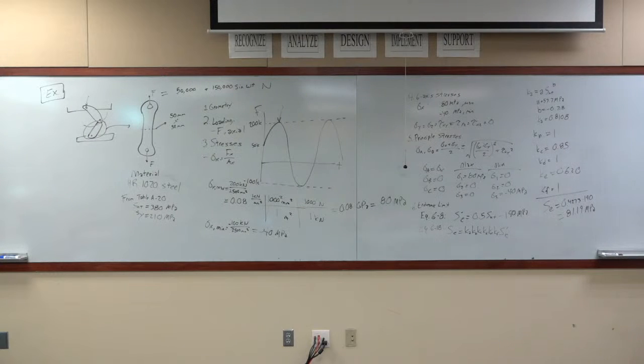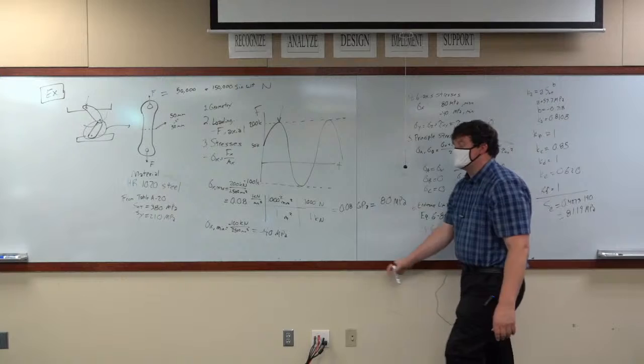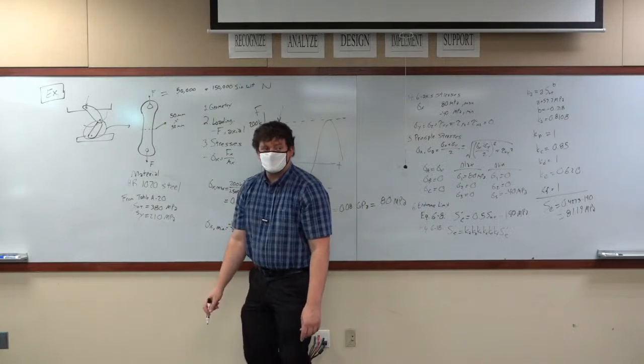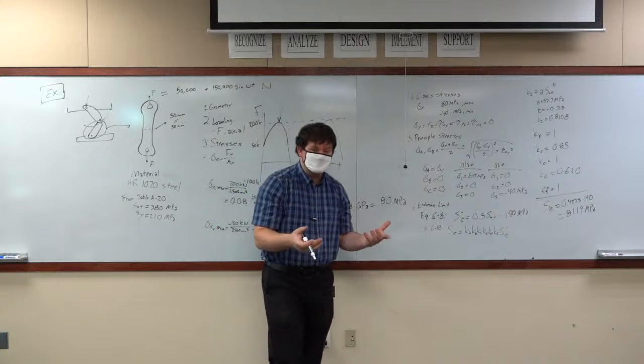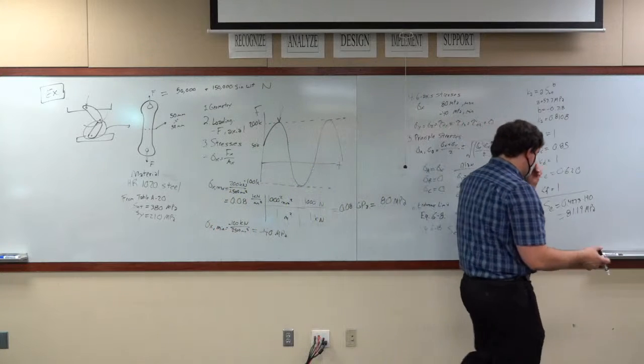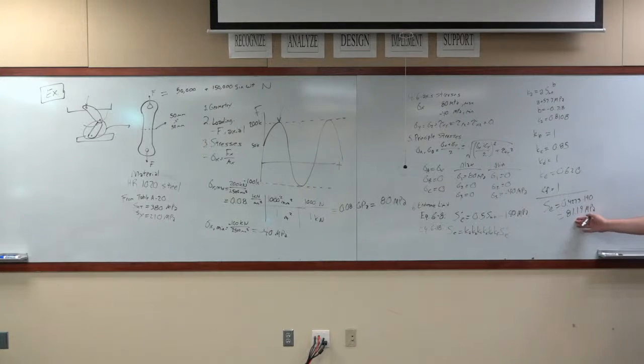Oof. Question, which is higher, the yield strength or the endurance limit? What? Yield strength, by how much? I'm going to take, Sean, your eyes got really big. I know what that means. By quite a bit. This is substantially smaller than the yield strength. Okay? This is one of the reasons why fatigue is so prevalent in materials and why we have to consider it, is because this kind of loading is much easier to reach than that one over there.